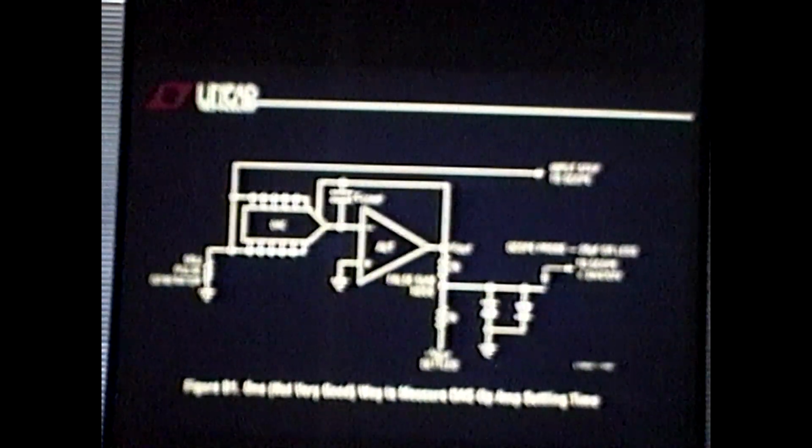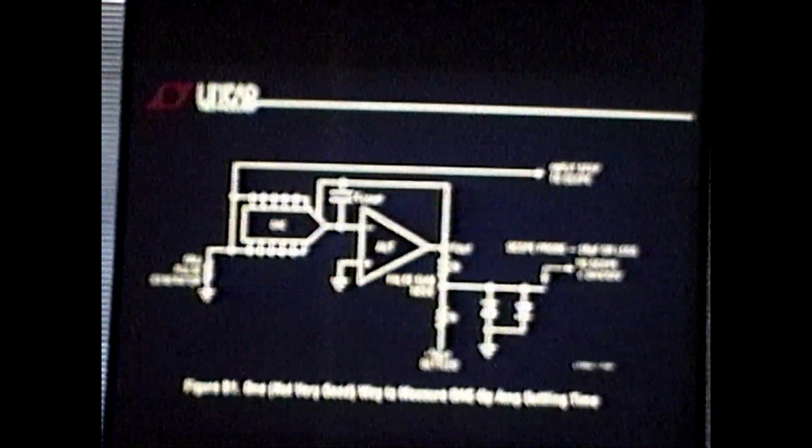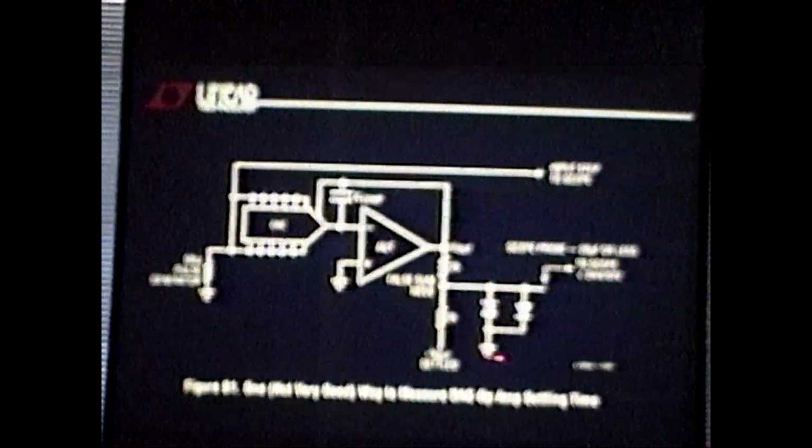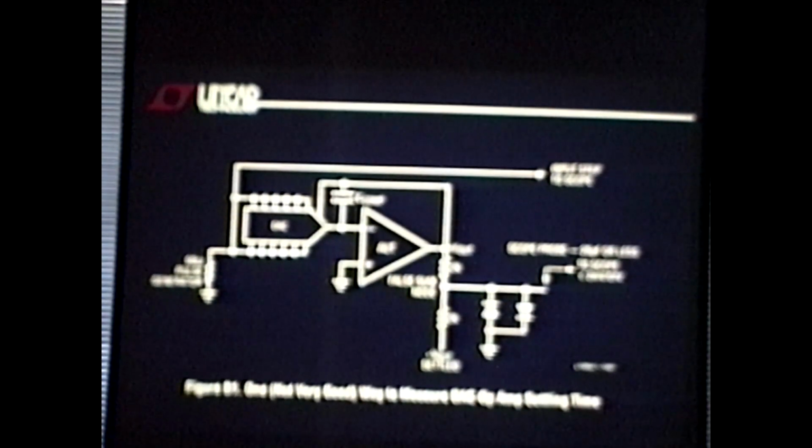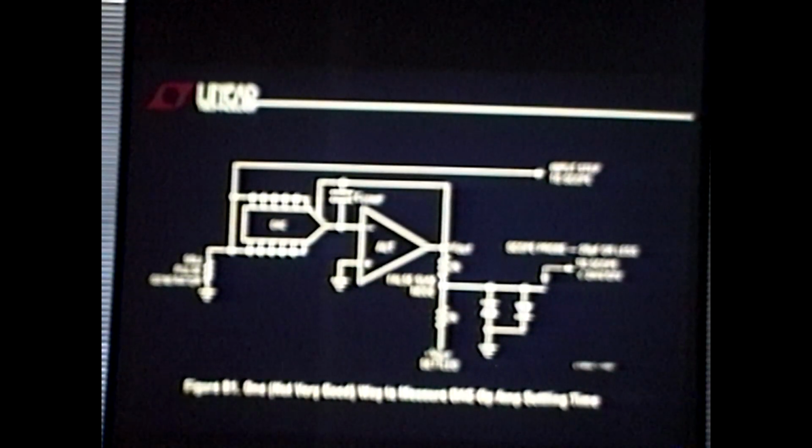We're going to sample. You wait until some length of time when you think you're well inside the clamp provided by these diodes, then you close the switch. So now they're going to see a very limited overdrive. So the name of the game is knowing approximately when this thing is going to settle.